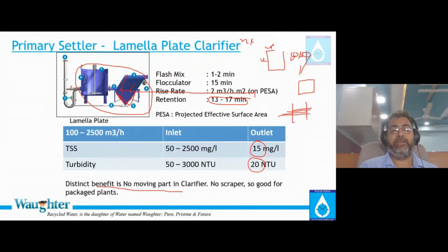And when they are sliding, they'll touch each other. And therefore, what is falling from here is a big globule. Okay, something maybe of this size, what I'm talking about. So if the big globules are flocculating, you can have this very steep angle of 45 degrees, and all the sludge will automatically go because of the weight and the force which is acting on the sludge itself. So you don't require a scraper mechanism to guide the sludge toward the sludge hopper.